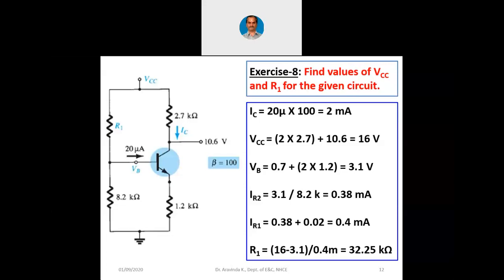So in such a case, as the charge carriers in the collector region are much larger in number when compared to the number of charge carriers at the base, there is already a current amplification factor within the transistor. That is because of the construction of the transistor itself. Now because of this, at the input the current is lesser and at the output the current is larger. This is with respect to common emitter configuration.